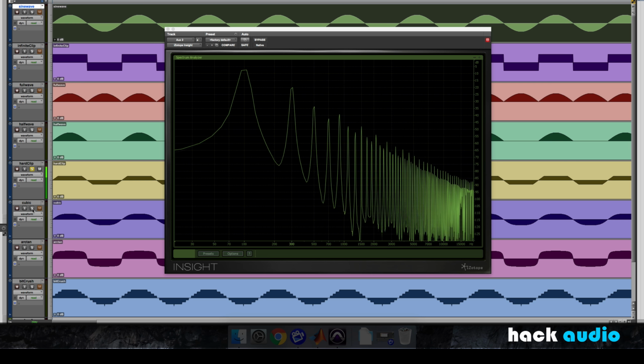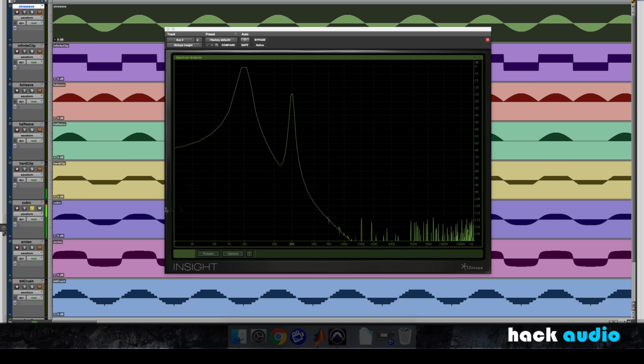First up, we'll look at cubic distortion. This is a type of soft clipper. Again, this is an odd function, so we'll get odd harmonics. However, in this case, when we take the signal and use the cube of the signal as part of the function, we're going to end up with this spike here at the third harmonic. We've got a spike at 100 hertz and 300 hertz. In fact, the amplitude that we use for the cube of our signal is going to determine how high the amplitude of our third harmonic is. If we decrease the amplitude of that cube part of our function, it's going to decrease this spike.